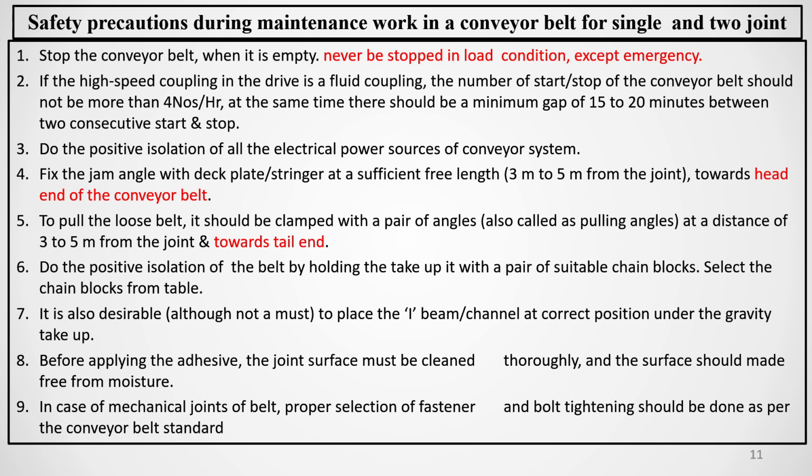When you have decided to repair the belt, first remove all the materials from the belt. When all the material is removed, at that time you stop the belt. Never stop the belt in loaded condition, then it will be very difficult. You have to remove the material, and cleaning is required.